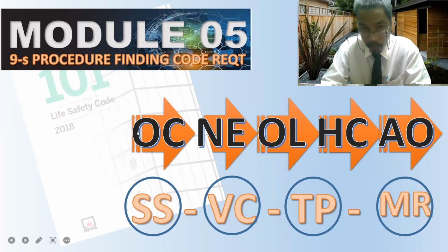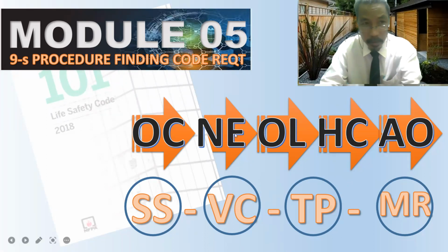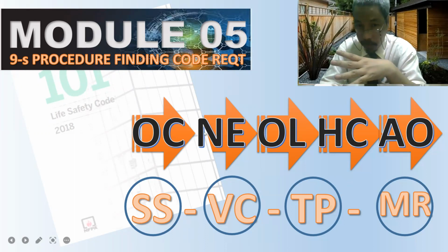So after looking at this 9, we can always take it into our mind. Occupancy class, of course, is the first one that we need to know. What is the classification of our application? Is our application new or existing? Then go to that part. How to calculate the occupancy load of our application based on the existing and classification? We can compute.